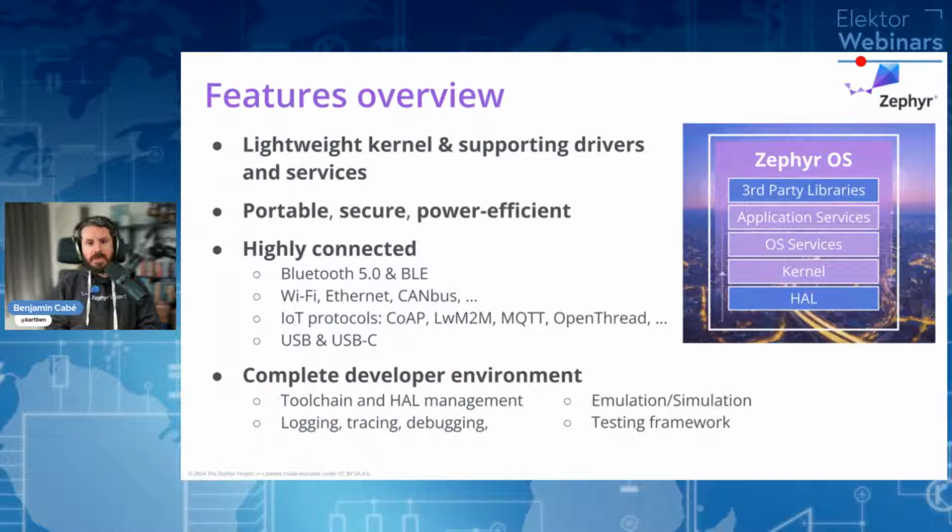But what's going to really save you a lot of time is other layers and other aspects of the system, and other aspects of Zephyr in particular. One being, sure, you have a scheduler, but you may want to run your application on a variety of MCUs and dev kits and varieties of silicon, right? And ideally, you don't want to have to rewrite or port your application when you're moving from an ARM architecture to an ESP32 architecture, et cetera.